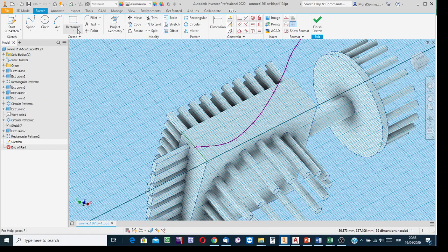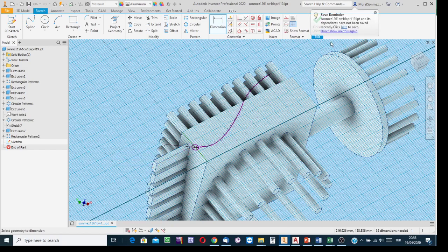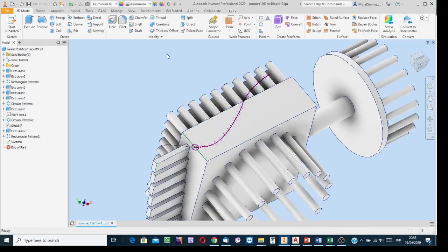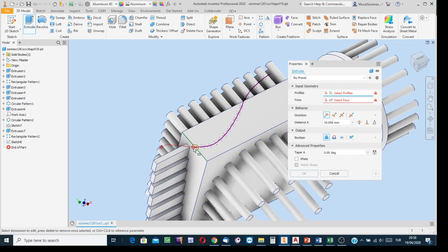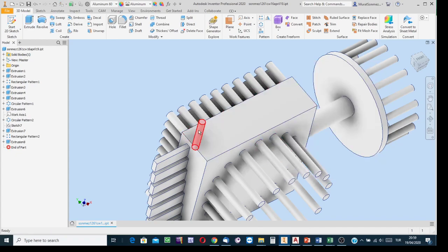And then, in this example, quickly finish the rest. About this point, create a circle. Size it. Its diameter, let's say, is 10. Okay. And then finish the sketching stage. Click on the finish sketch button. Apply the extrusion process first to create the model of the first member. It is over here. Say that its length is 60. And then say OK. Well, this is the first member.